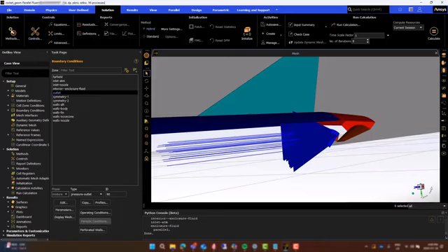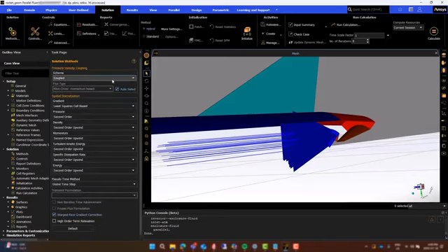Next, we'll set up the solution numerics in the Solution tab, selecting Methods. We'll use the coupled scheme, which solves for pressure and velocity simultaneously and is best used when these components are highly dependent on each other, as is the case in compressible flow. Green-Gauss node-based method is used for gradient discretization, and everything else is set to second order to reduce numerical diffusion. Ensure that pseudo time stepping is enabled, which automatically controls the time step in each cell, and enable high-order term relaxation, both for numerical stability.